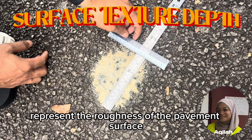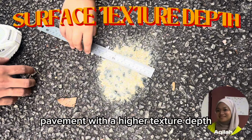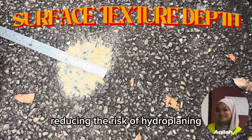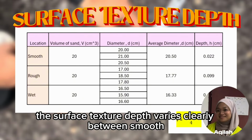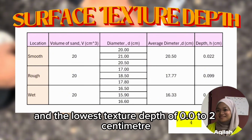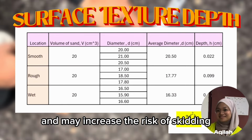This value represents the roughness of the pavement surface, which directly influences both skid resistance and water drainage capability. Pavement with a higher texture depth generally provides better friction and allows faster removal of surface water, reducing the risk of hydroplaning. Based on the sand patch method results, the surface texture depth varies clearly between smooth, rough and wet pavement surfaces. The smooth surface recorded the largest average diameter and the lowest texture depth of 0.022 cm, indicating a polished surface with minimal microtexture. This condition limits water drainage and may increase the risk of skidding.